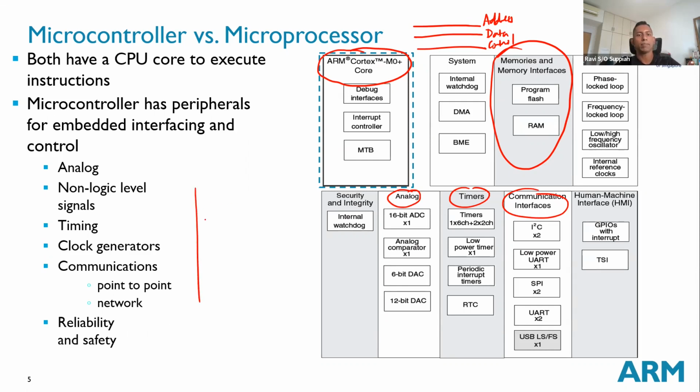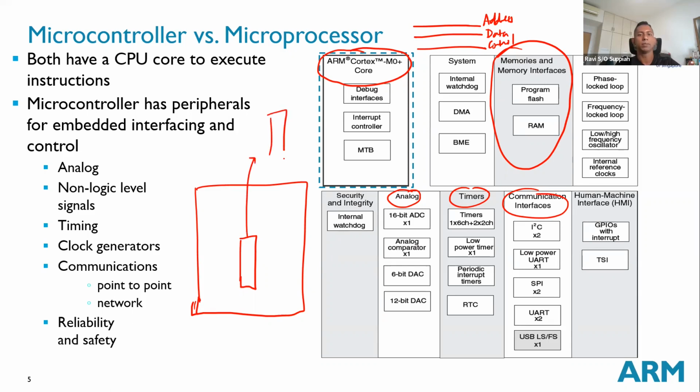Okay, the board is actually very big. If you look at the Arduino Uno, for example, since we are familiar with that, the chip itself is only that small single chip. So if I want to build my own custom board, all I need is to extract out that chip, put the power and the ground, and that's about it.